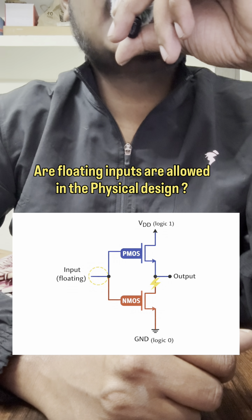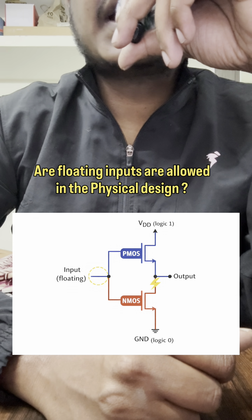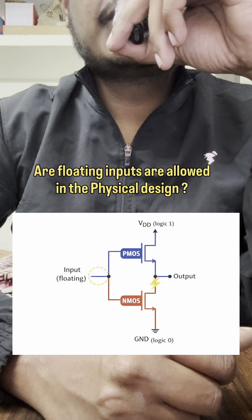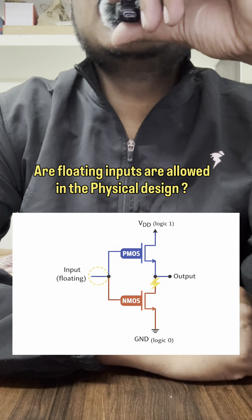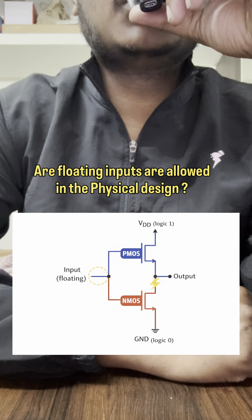This is why in ASIC design, we always connect unused inputs to a defined logic level using tie high or tie low cells. Floating inputs are never allowed in proper digital CMOS design. This leads to short circuit current, increased power consumption, and unpredictable output behavior.